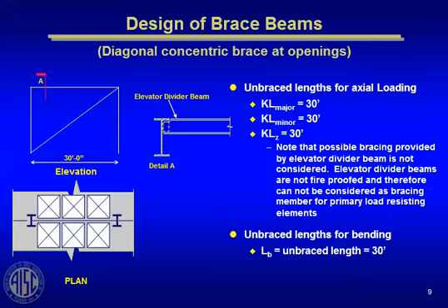And the same applies here for the diagonal brace. So be careful about the openings and the unbraced lengths that you're assuming.